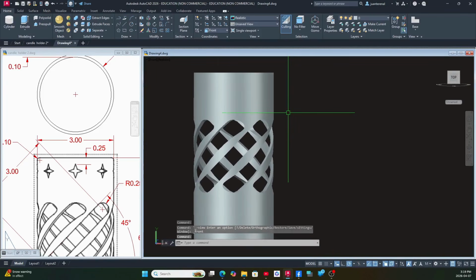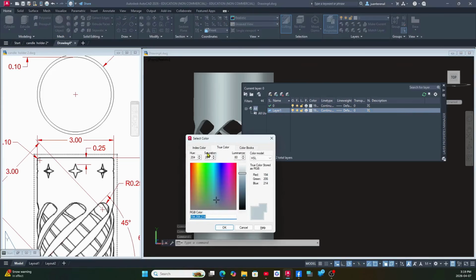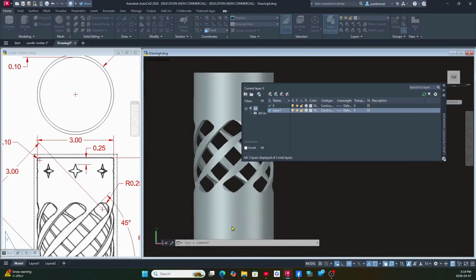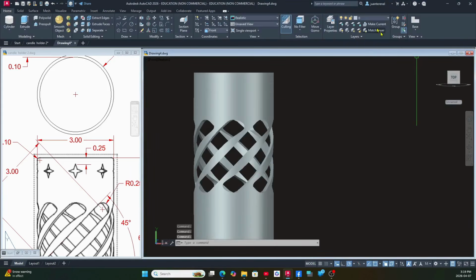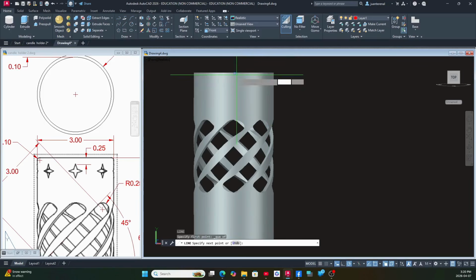and create a construction line. It's easy to see. So go to layer and create a layer; for a construction line, I'm just going to use red. It helps a lot when the color is different. Okay, and bring it current, so layer red, or you can name it, but I don't bother. So L for line, shift right click, snap the quadrant, go downward for 0.25.